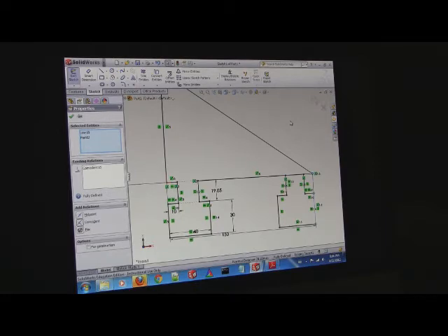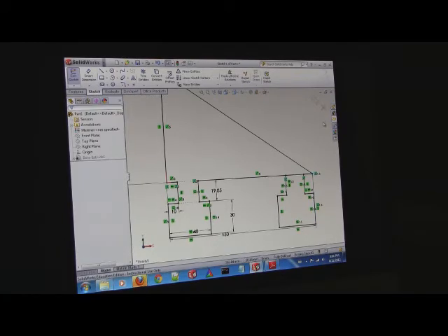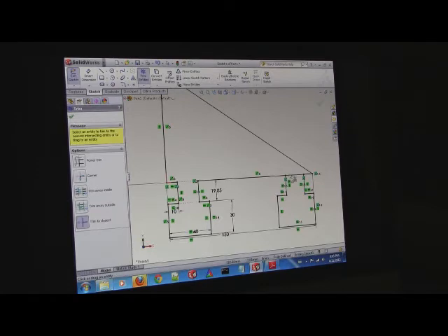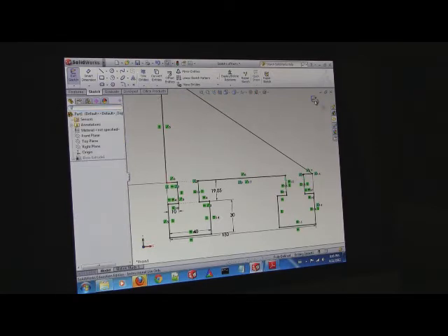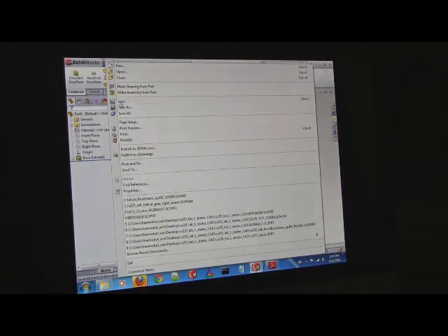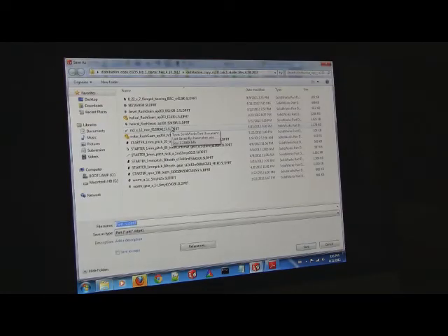Did everybody's line up? Just so you know, if you didn't do it perfectly, it's going to complain bitterly. Alright, are we extruding? Not yet, because we still have this line here that we need to get rid of. Hit trim, get rid of that little segment there, and now go ahead and hit the purple check mark and make sure it still extrudes, and then save as whatever you want.